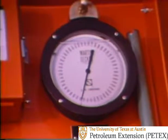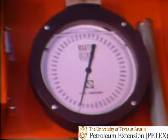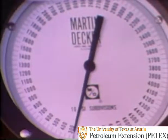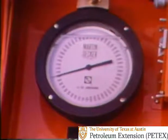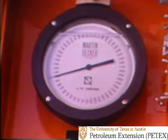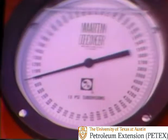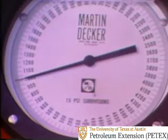As the heavier mud is circulated down the drill pipe, the casing pressure is held constant at the last observed circulating casing pressure until all of the lighter mud in the drill pipe is displaced. Then the pressure control is moved back to the drill pipe until the heavier mud fills the annulus. When the heavier mud reaches the flow line, the drill pipe pressure should have reduced to the pre-selected circulating pressure, in this case 1,000 psi.